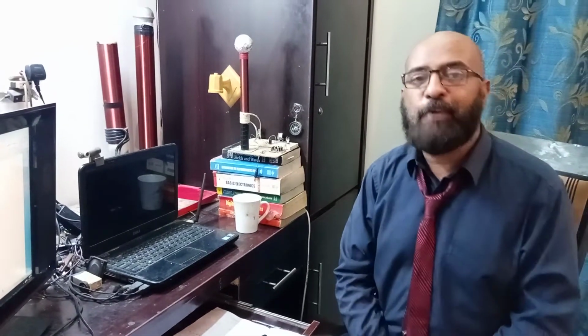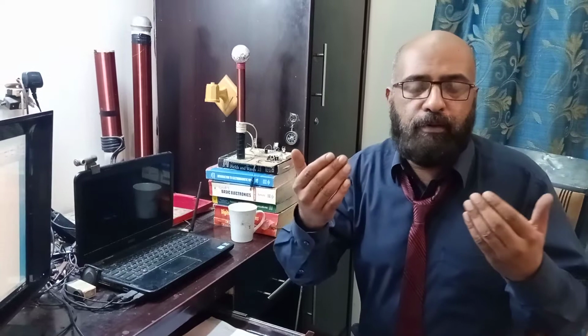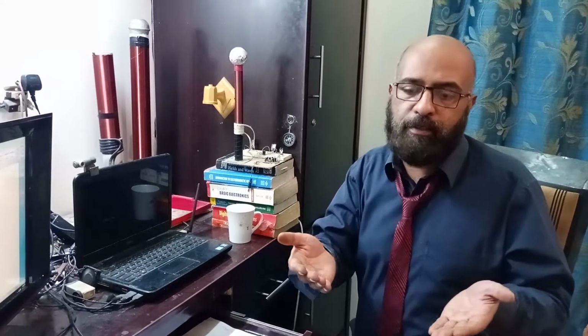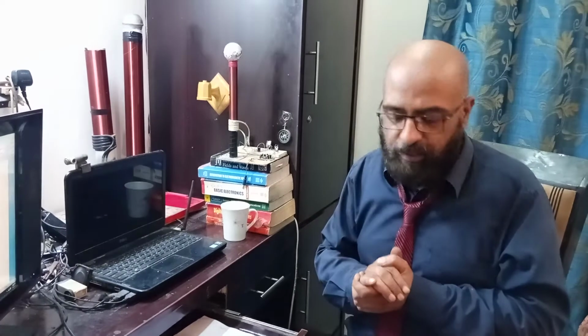When we are talking about electromagnetic waves, they are disturbances in 3D space, right? And these disturbances get weaker and weaker as you increase the distance from your transmitter to the point where you are observing them, following the inverse square law. So it's obvious the power that you are delivering to your transmitter will not be equal to the power on the receiving side, right? So we need a mechanism to calculate the receiving side power density.